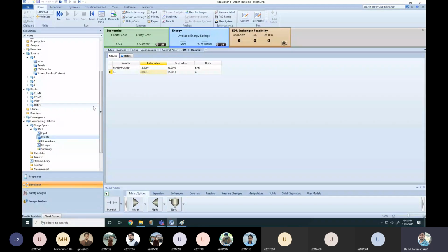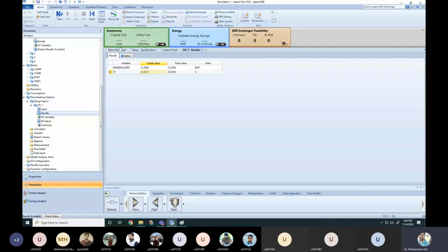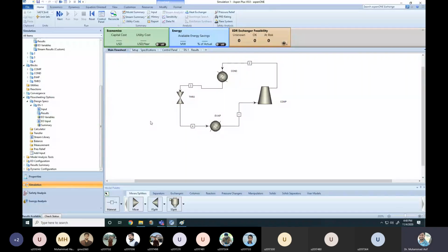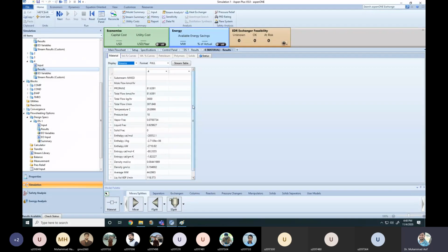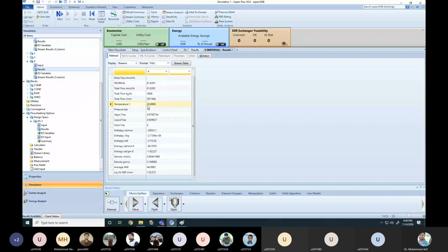So let's say I want to put another design specs, right? Let's say I want to get, at stream 4, a temperature of 10 degrees C. What is the temperature now? Let me see the temperature now. Now it is 26.89 degrees C, right?